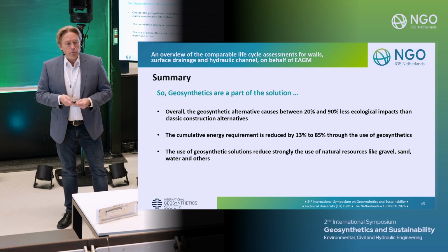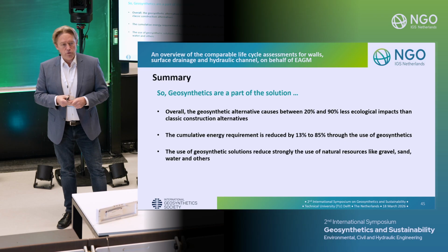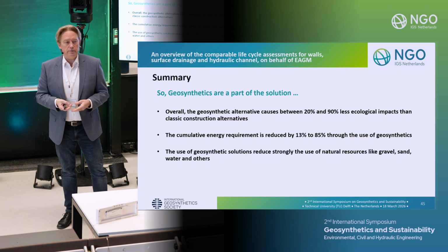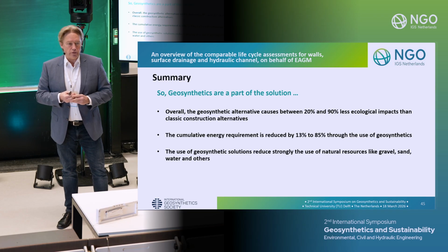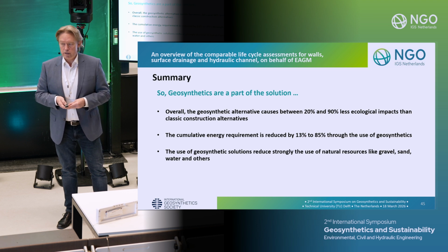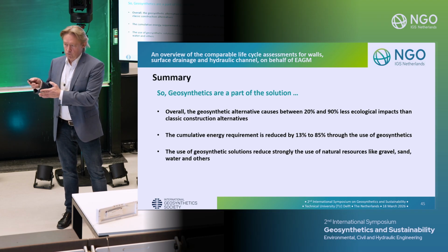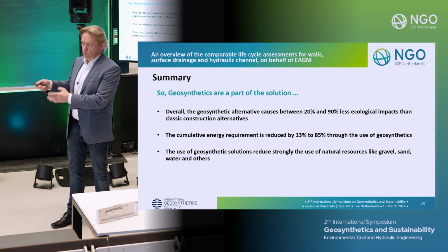Nevertheless, we also reduce the use of natural resources like clay, gravel, and sand. Kent mentioned this example, that you have to use water to prepare the compacted clay liner. What he didn't mention is you have to use fresh water. Here, especially in the Netherlands, you have a lot of water around, but you can't use this water for bringing the compacted clay liner to the right setup. You have to use fresh water. So it's not only that I have to save water, I have to save really special water.